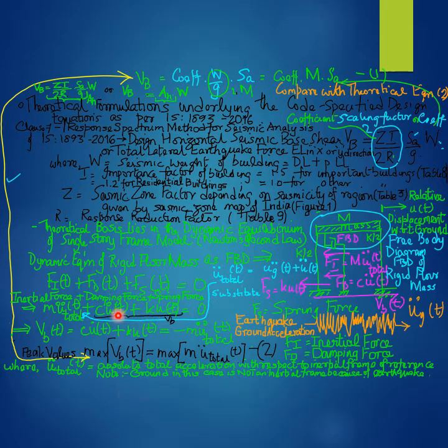Therefore, for purposes of applying Newton's second law, we consider a point distant from the earthquake site or the building site that is not subjected to earthquake ground acceleration and therefore qualifies as the origin for an inertial frame of reference, provided the point or the origin is not accelerating for any reason.